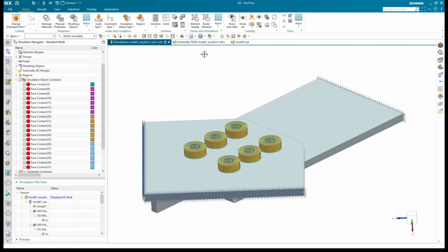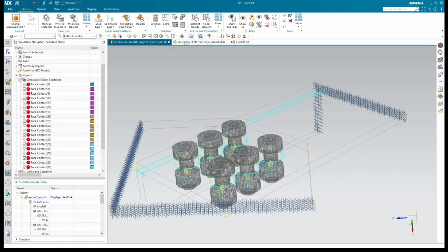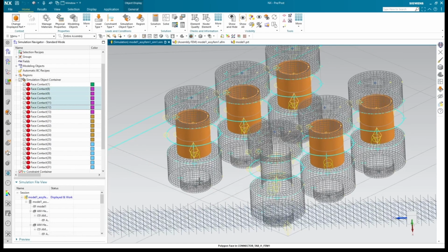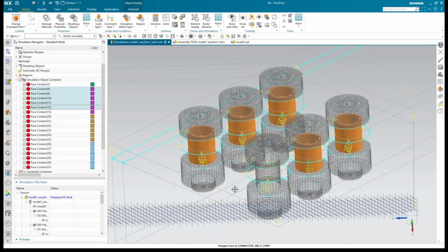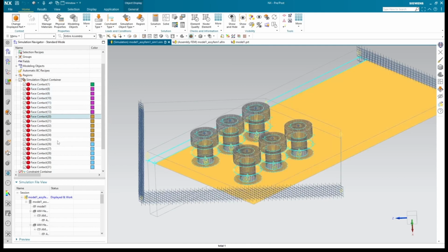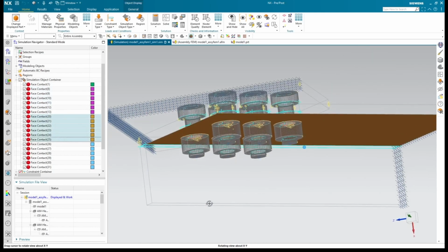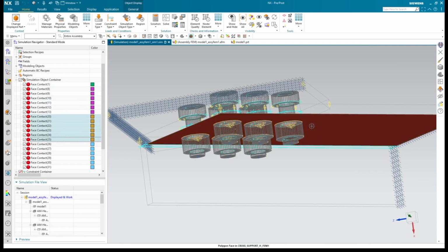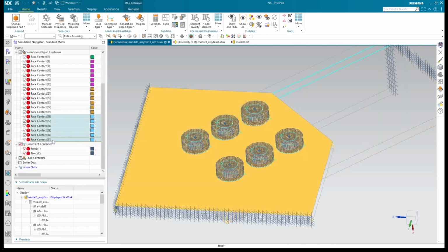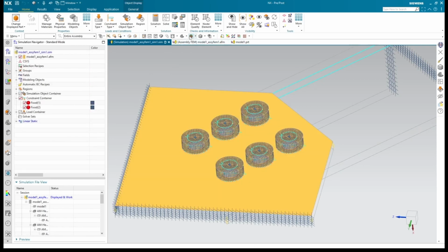All the components are in contact together, so I have applied the surface to surface contact. You can right away change the rendering style and review the surface to surface contact. Here you can see that the bolt shank and holes are in contact, so I have defined a contact there. We know that our nut and the bottom surface of this plate are also in contact, so I defined a contact there, and our bolt head is also in contact with the top face of the connector tab. So I have defined a contact definition there and applied a friction coefficient of about 0.8.